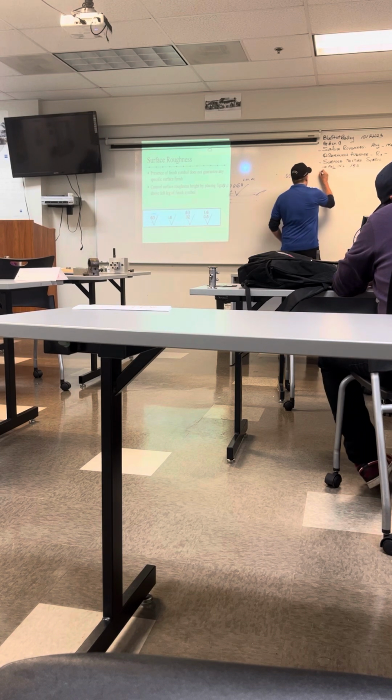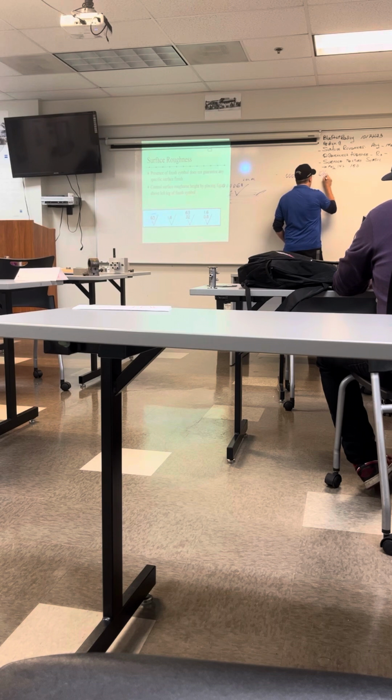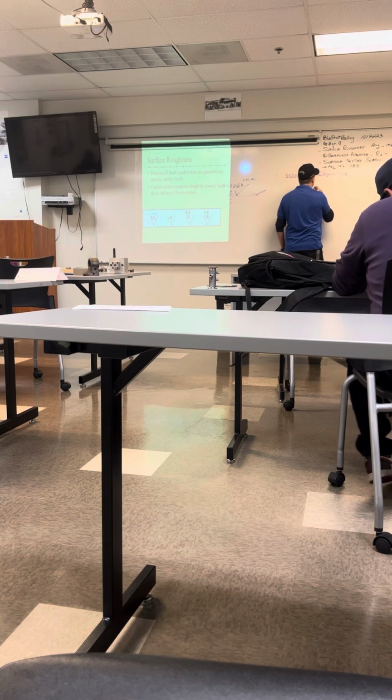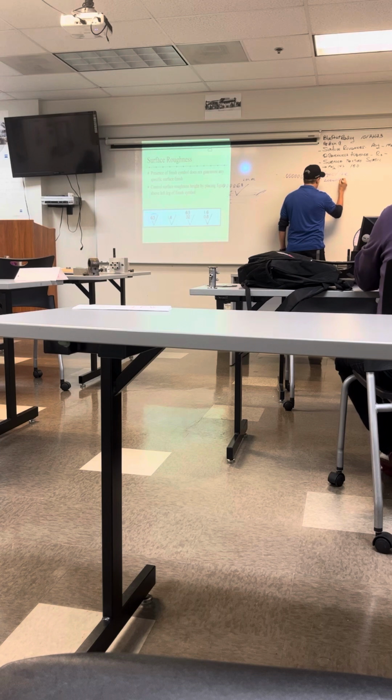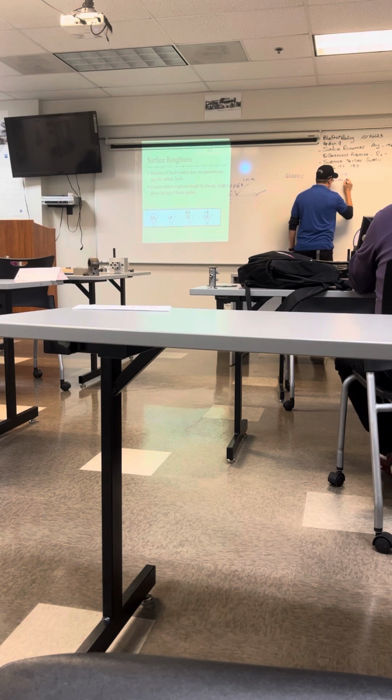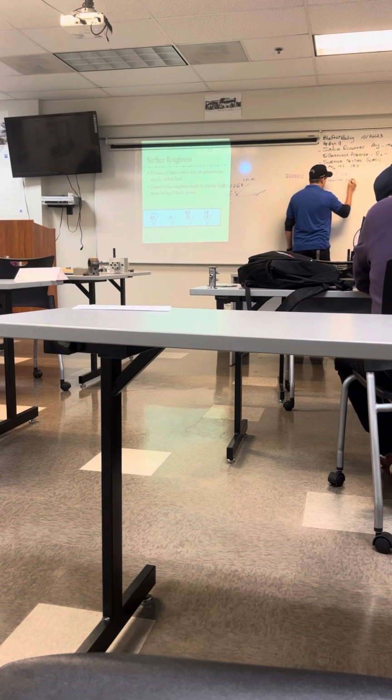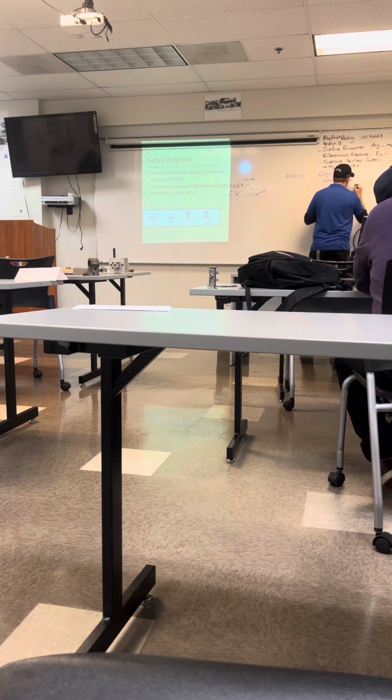These figures represent the mathematical average deviation from the roughness center line and are expressed in microinches, millionths of an inch, or micrometers, millionths of a meter. The figure 63 above the left leg would actually represent 63 millionths of an inch,